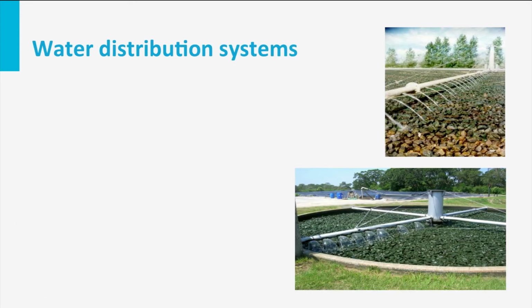Proper water distribution, or wetting the biofilms, is considered crucial. Most trickling filters are equipped with a rotating arm, which rotates by water pressure. In order to achieve this, the orifices are positioned only at one side of the arm. The length of the arms is generally not more than 40 to 45 meters.